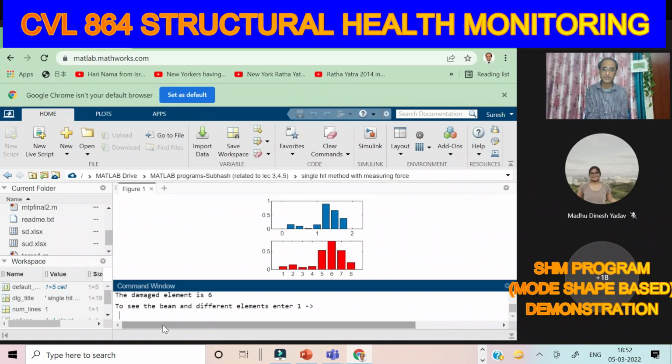So what you see here, the second plot, shows the element number. It has divided the beam into 8 elements because there are 7 sensors. And what we find is which element is damaged? The 6th element is damaged because the 6th element has the highest value of the change of curvature. So basically these mode shapes are the curvature mode shapes, and here the 6th element has the maximum value. So this is the damaged element.